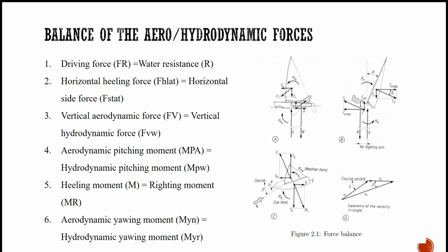So how does a sailing yacht navigate with a constant speed? This phenomenon is the consequence of the balance of the aerodynamic, hydrodynamic, buoyancy, and gravity forces. These forces in turn depend on the wind strength, the shape of the sail, type of rig, and control gadgets. In addition to that, they depend on the size and the shape of the hull, displacement of the boat, distribution of the weight, and finally the sea conditions and the crew's level of expertise.